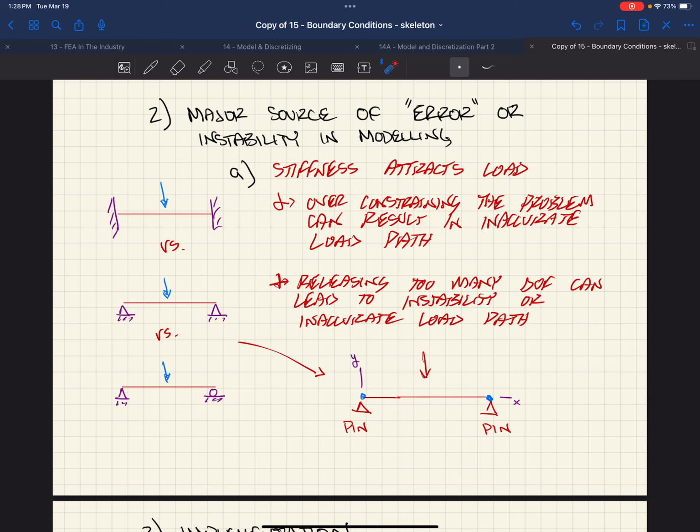And the fact that we do this in a single step, okay? So you might be able to do P delta on this, but there are no axial loads that will be developed in this bar. So you would have no instability created based on P delta because of the fact that VA does it in a single step, right? We solve the initial problem and then we add that geometric stiffness matrix. And because we're taking equilibrium about the undisplaced shape, as we see here, there is going to be no axial load in this member.